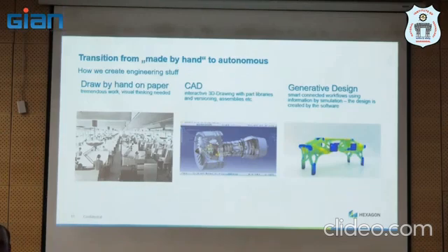So it can come up with unique shapes for 3D printing. And the advantage of 3D printing, the complexity comes for free. So if some design is not complex, better not to go for 3D printing because it can be easily manufactured by conventional ways. When design complexity comes, 3D printing can be easily justified.